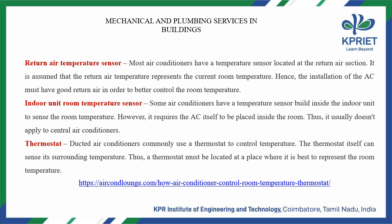Return air temperature sensor. Most air conditioners have a temperature sensor located at the return air section. It is assumed that the return air temperature represents the current room temperature. Hence, the installation of the AC must have good return air in order to better control the room temperature.